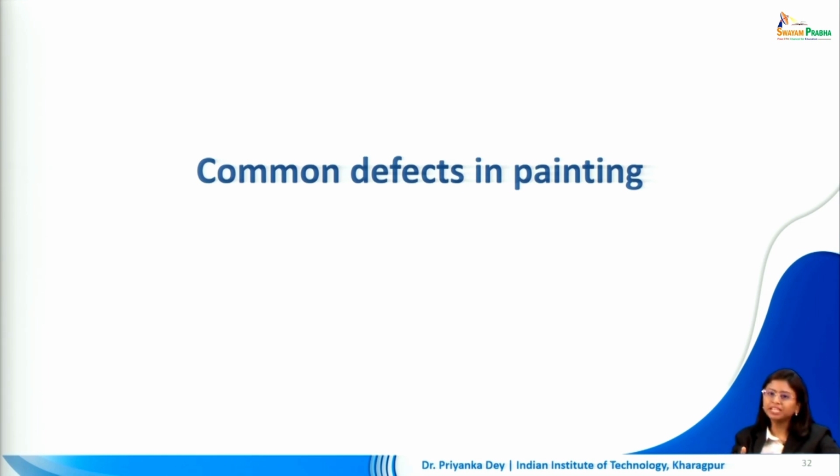The type of paint we select will also be determined by the background or the surface on which we are painting. So just like we had learned in plastering, if we are dealing with stone masonry walls, brick masonry walls, timber or metal lath, we have different number of coats of plaster. Much like that, the type of paint that we are selecting will also be determined by the background material that we were dealing with and the amount of protection that it needs over time.